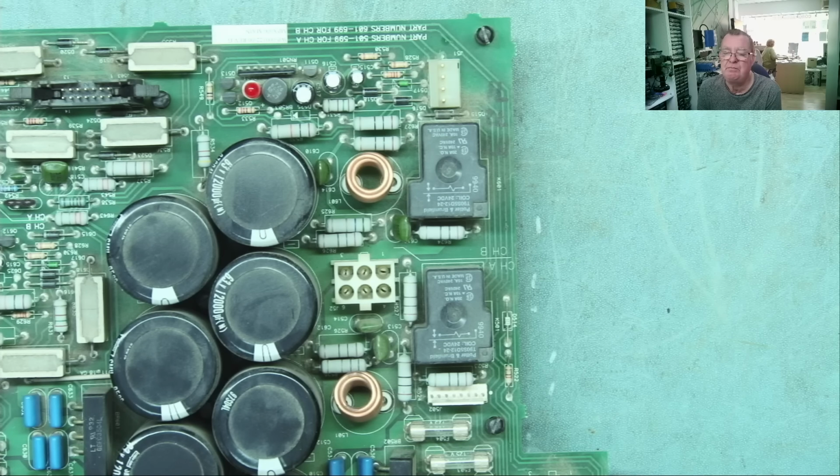The only real way to repair those is to actually unsolder the multi-pole switch from the board, for which you need something like a vacuum desoldering gun to be able to do it. Take the switch apart and actually get to the metal contacts themselves and clean them, yeah, with something not too abrasive. Put it all back together, because you can't get those switches. Maybe if you're lucky you have a scrap donor, but the chances are the switches are in much the same condition as the one you're trying to replace. And I have done this sort of work. This is more what I would class as restoration than repair. It takes some time but can be very satisfying.